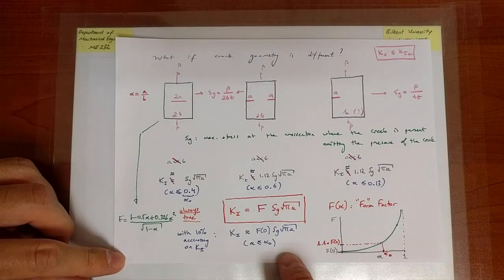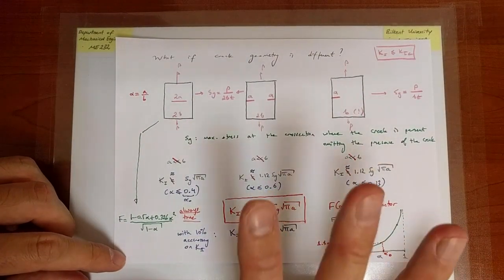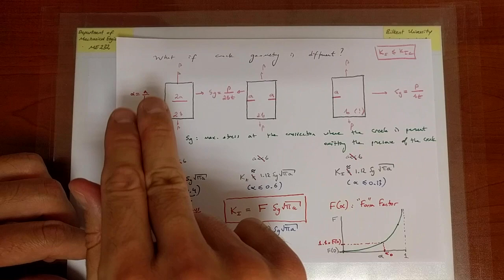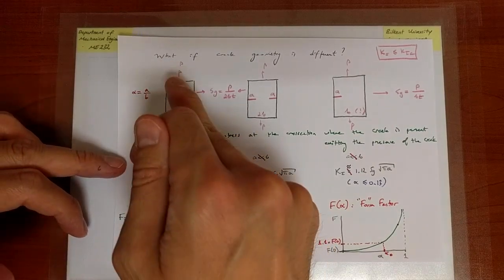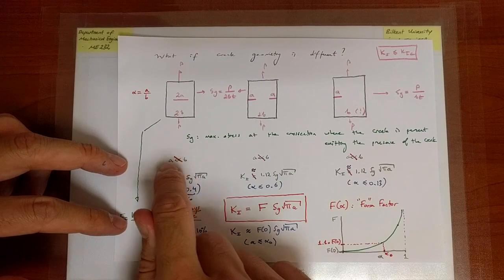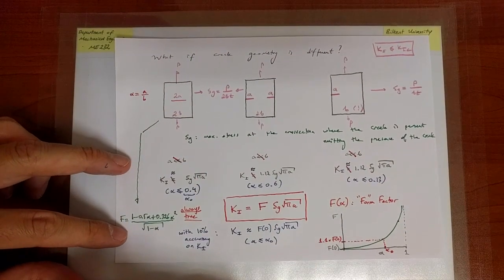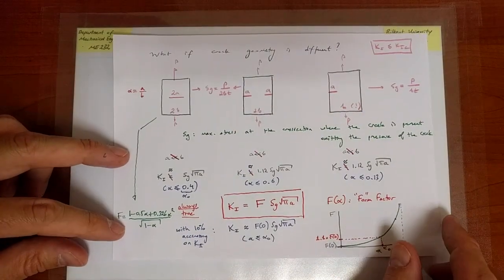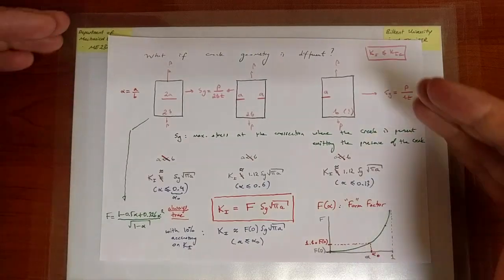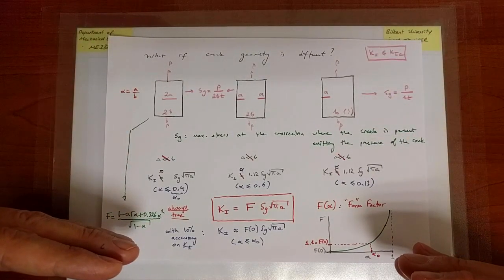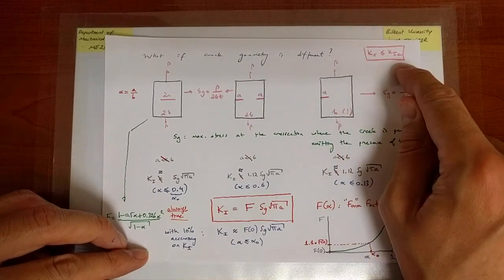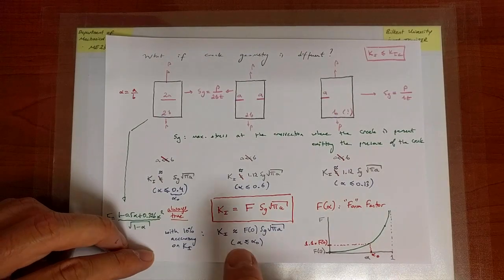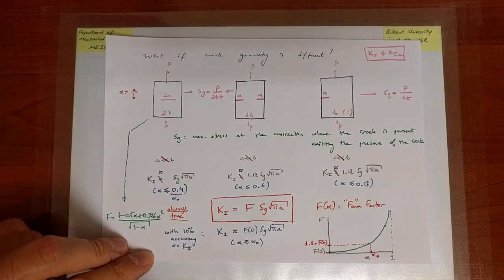All right. So now this is the case that we have looked at, and what we've considered is the generalization from our ideal geometry by saying that, well, perhaps the width of the crack is actually not that small, and also perhaps the geometry of the crack is not actually the same in every case. And what we've done is we've generalized the expression for determining K1. The criterion is always the same, but the expression is slightly generalized by incorporating a form factor, and now this is an expression that is always true.